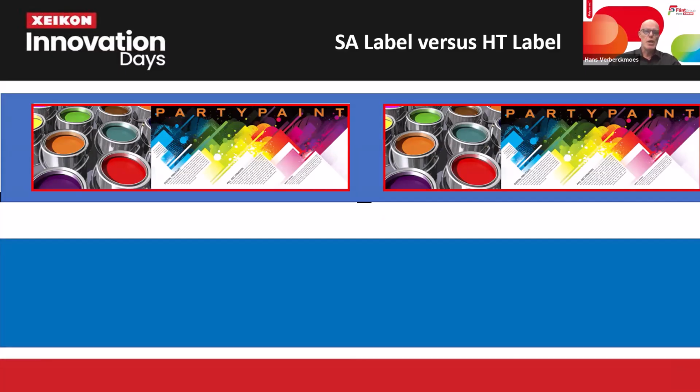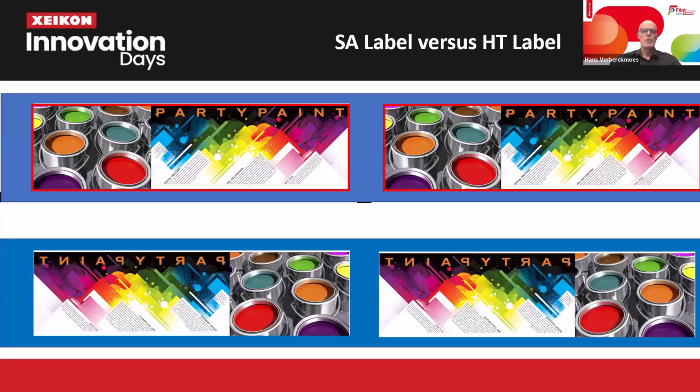When we talk about a heat transfer label, we don't have a face stock. We print immediately on the liner, meaning mostly a silicone coating. It must be a release layer. We print the image, and here you see the second difference: it's reversed. You always print your image in reverse, because after transfer, your image must be readable. And then last but not least, we also add a marker, because a lot of the applicators used in heat transfer need to be triggered and need to know when to apply the label onto the object. So we add a marker onto it.